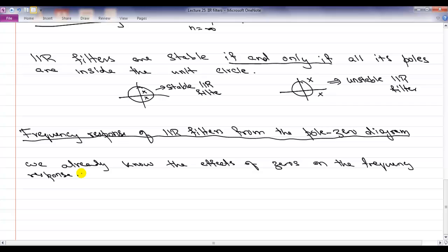Okay. Now let's look at what happens in the case of poles, or when you have both poles and zeros. In that case, a general form of your frequency response is given by this: P0 over D0 e to the j omega n minus m, and then each zero contributes to some response in the numerator.